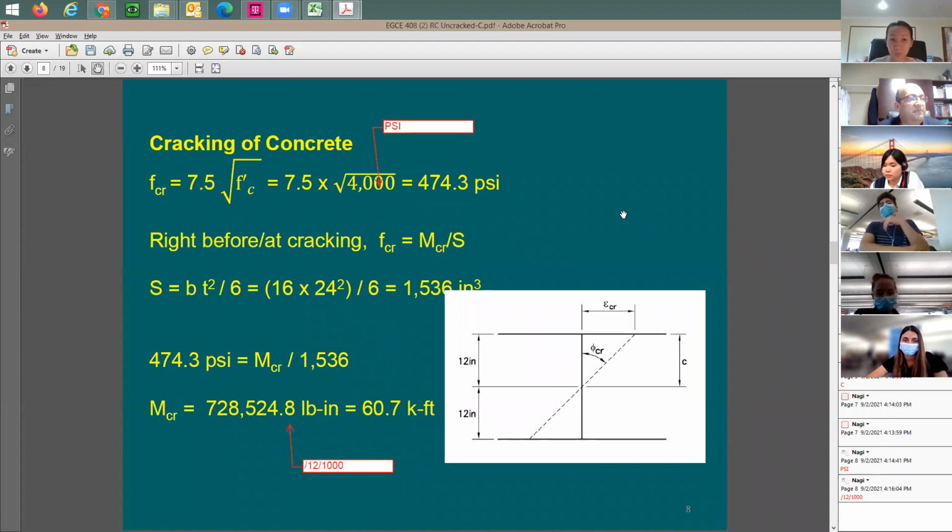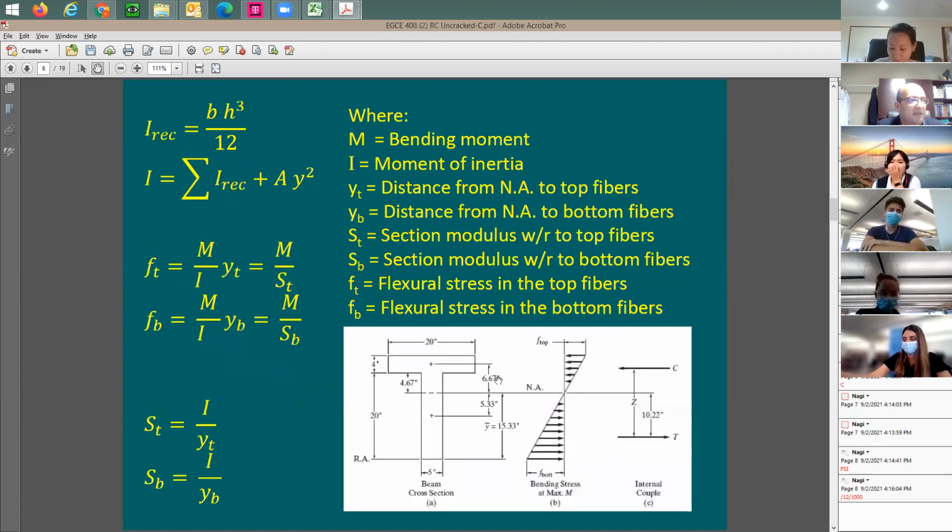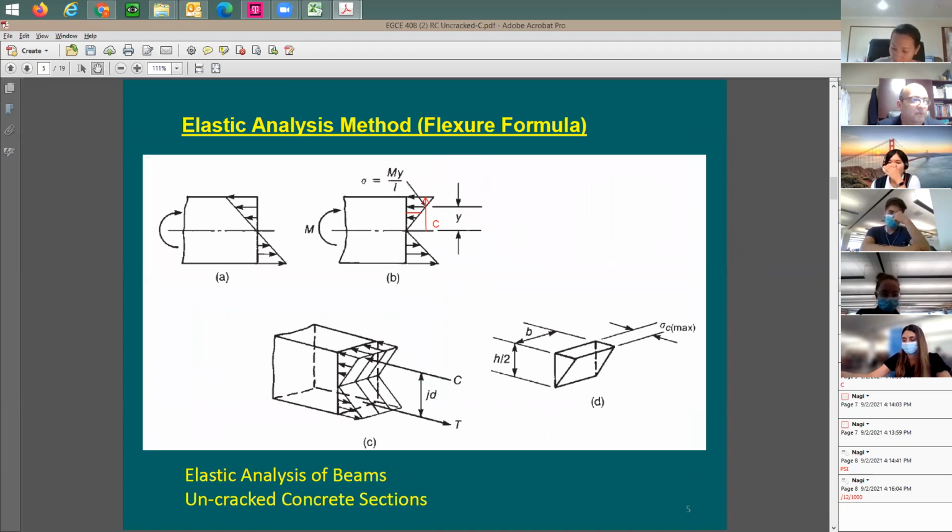All right, so previously we said that I can take this force here and make it, if I may go back here, 2 forces. We said that we're going to have 2 forces. One is going to be compression coming this side, and here's going to be the tension force. And we said in order for you to find out this force, you need to do integration. What does it mean by integration? Integration is going to be the area under the curve. But when you have a surface, what does it mean by that? It's going to be the volume below the surface.